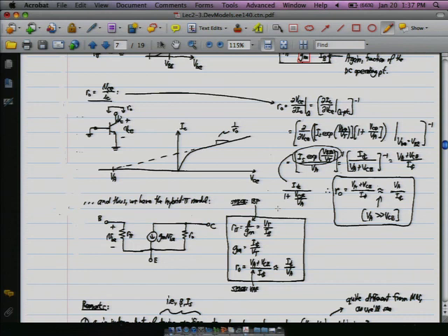And so going through a little bit of math, this basically just says we're evaluating it at the operating point, and then at the point that we have to actually do this derivative, this component goes away because there is no VCE term, and then this is all that remains.